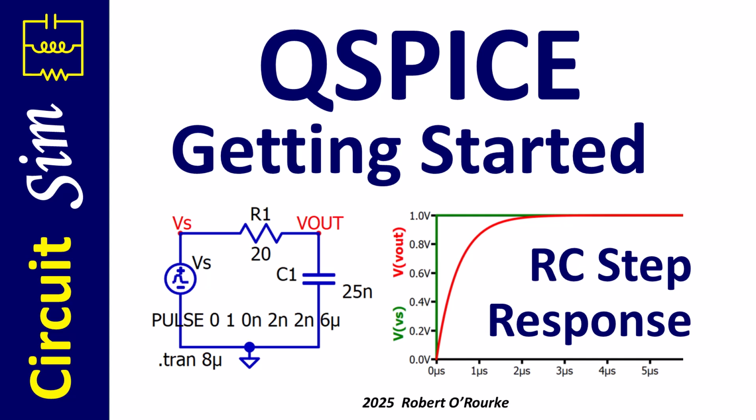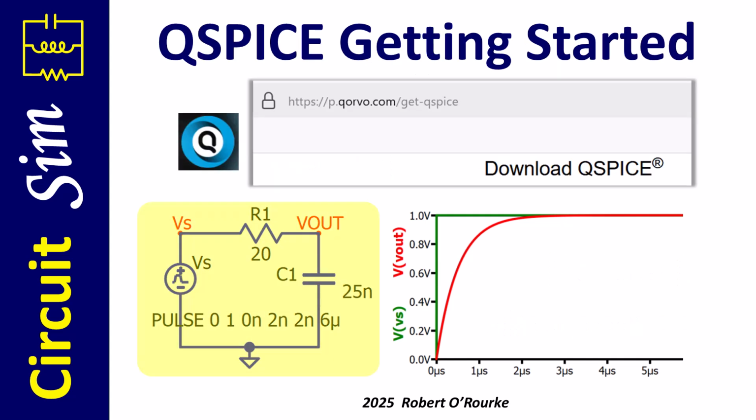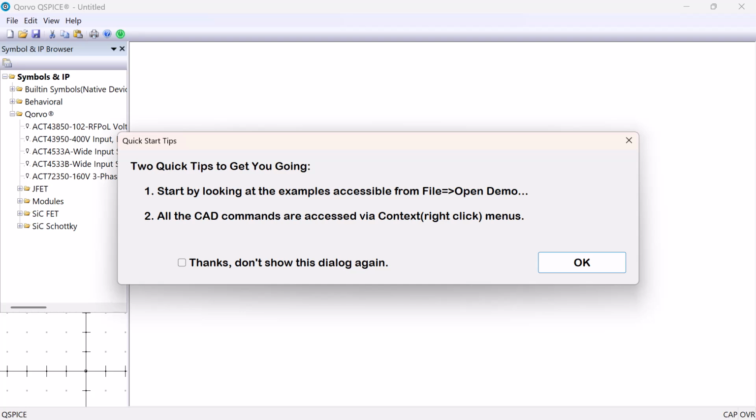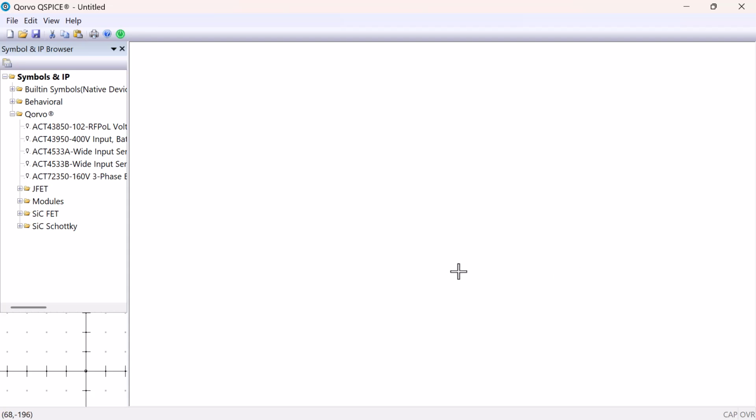Welcome. This video shows how to use QSPICE for brand new users, including circuit schematic setup, simulation setup, and plotting the simulated signals. When we invoke QSPICE, we get a helpful message about how to navigate the GUI. Here are the functions available with right-click.